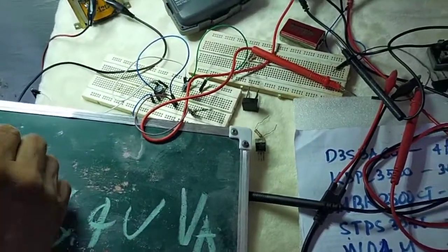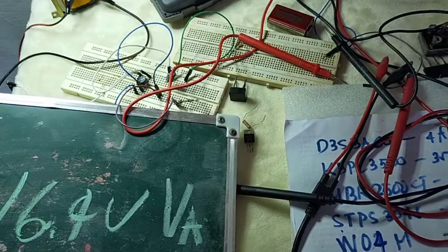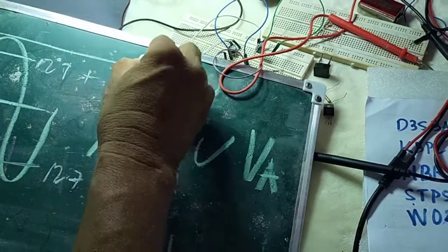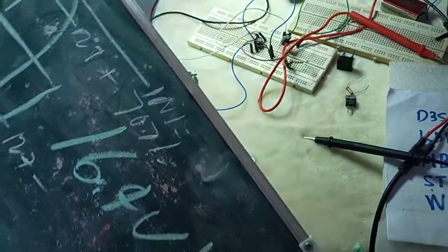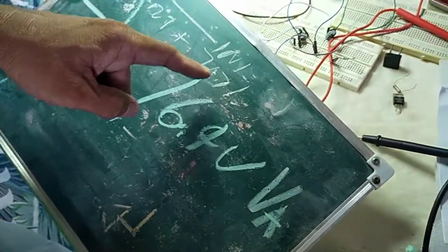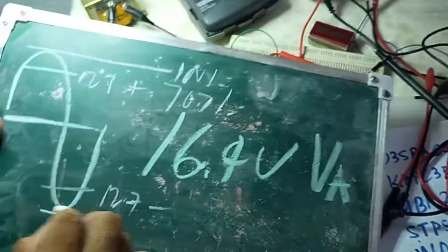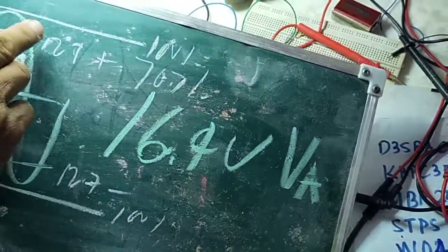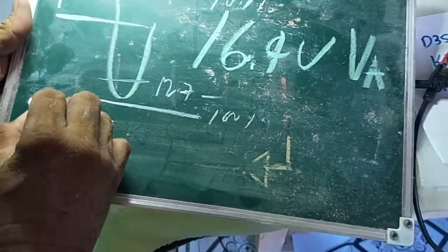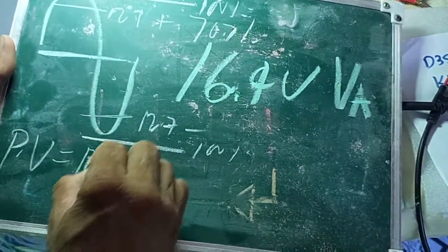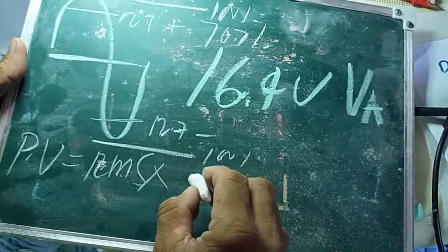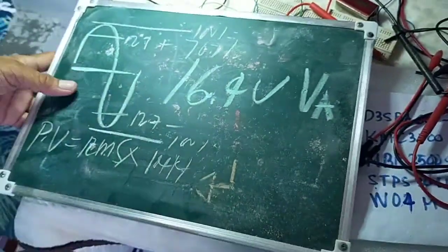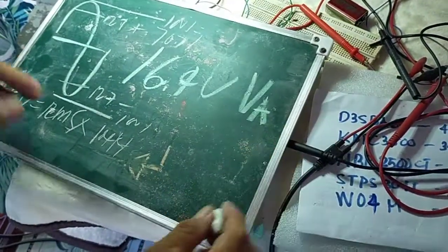12.7 volts here, positive. We have also 12.7 volts negative. It is only 70.7% of the peak value, which is 100%. What is measurable by your tester is only the 70.7%. Also here, we have 100%. So, what do you think is the peak value? Okay, let us compute. Peak value is equal to RMS times 1.414. 1.414 actually is a constant value.